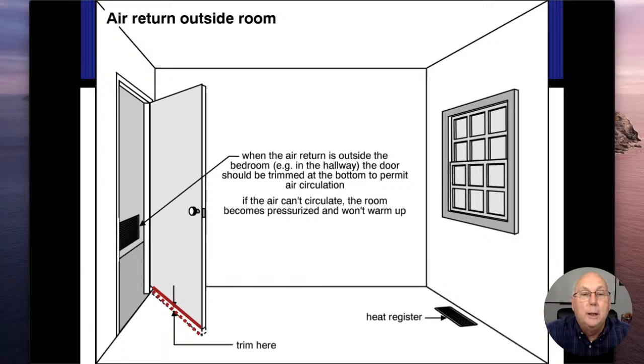All right. We also need to make sure that the air can flow in and out of that room with ease. Not only when the door is open, but when the door is closed. So these things are designed to have an undercut under that door, so that as I'm blowing air in, I can let the air get out. If I have carpeting or that opening's too small, that's going to restrict the amount of airflow that's coming out of there.